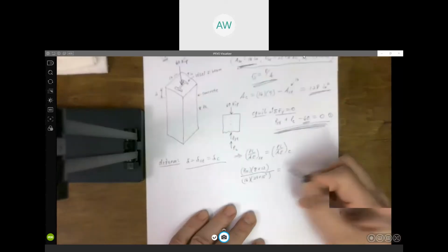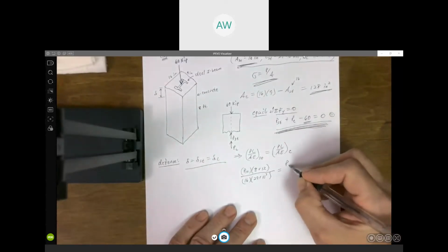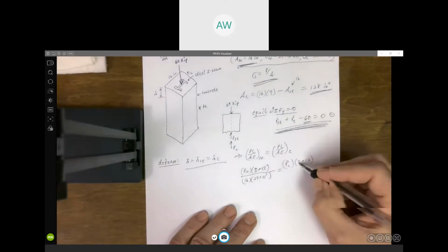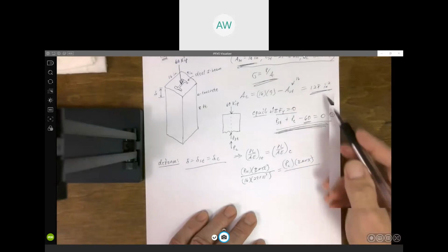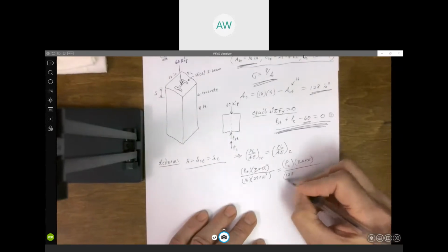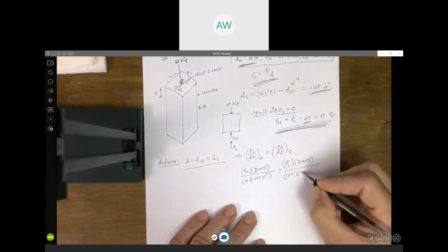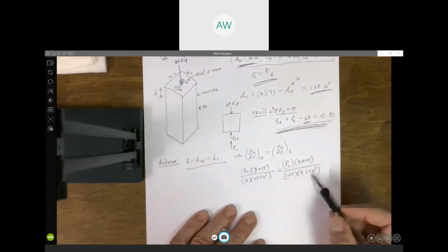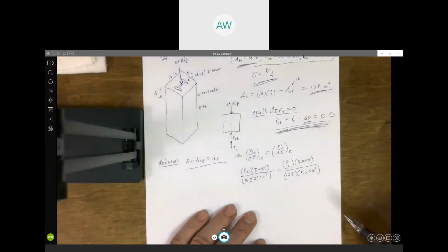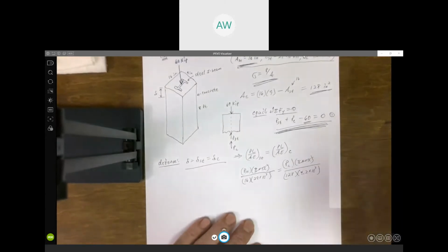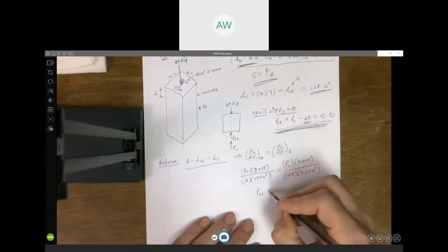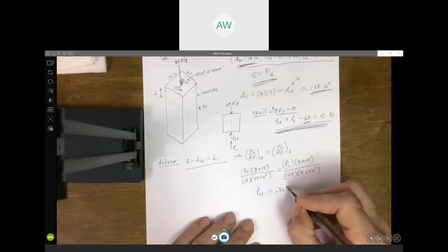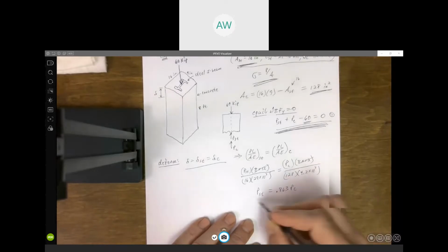All right, and over here I called the force in the concrete, PC. The length, again, is the same. Those are going to cancel anyway. The area we found was 128, and E for the concrete, 4.2 times 10 to the third. Again, KSI, as long as both of these are in KSI, this is in kips, our units are good. And then do some calculating with your calculator. I got 0.863 if you crunch all those numbers.